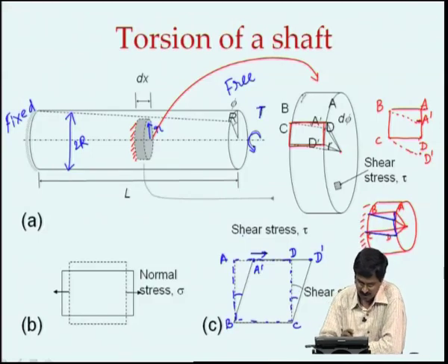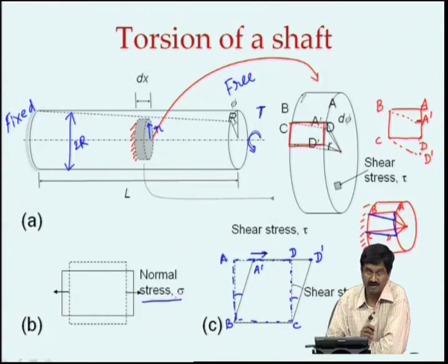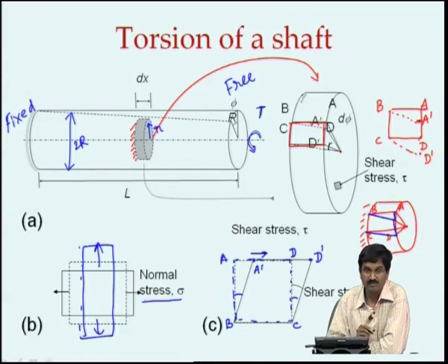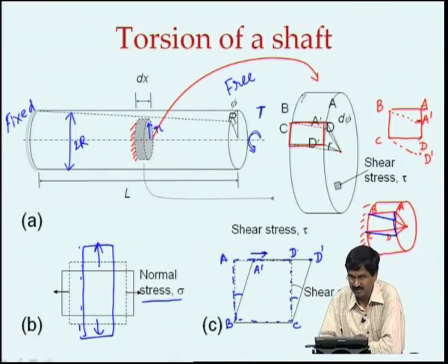That is something that we had not discussed at length before, but we did talk about normal stress and normal strain a lot. In normal stress and normal strain, you have a force applied normal to the surface that changes the volume of the body. If there is a stress here, it will go this way. If there were a stress here, it will go that way. The original one has become this rectangle. If there were a stress there, this can become a rectangle like that. That is what we talked about as normal stress. The shear stress is different from it. Here we apply force parallel to the surface. Here it is perpendicular or normal, here it is parallel. So that causes what we call shear strain.